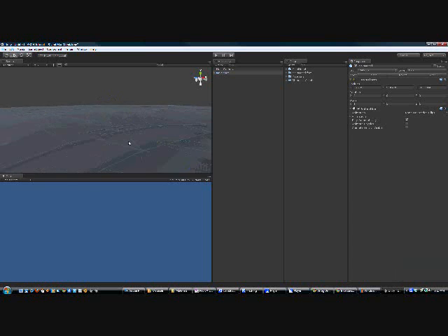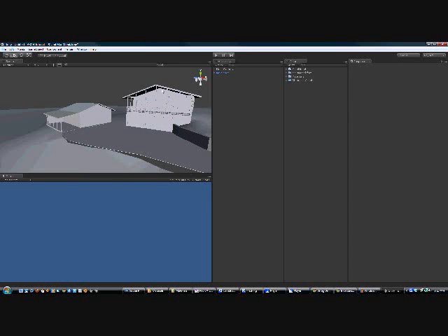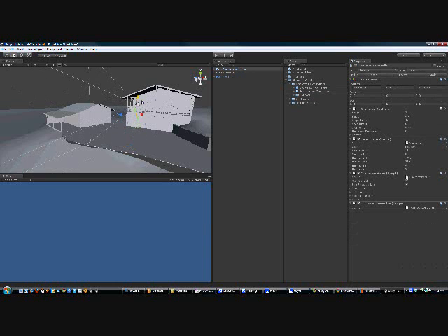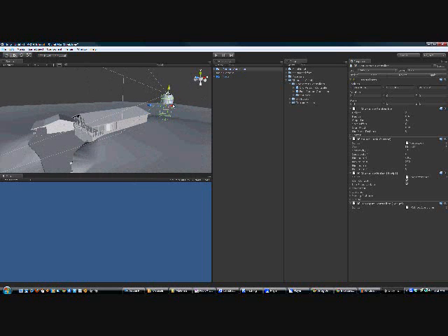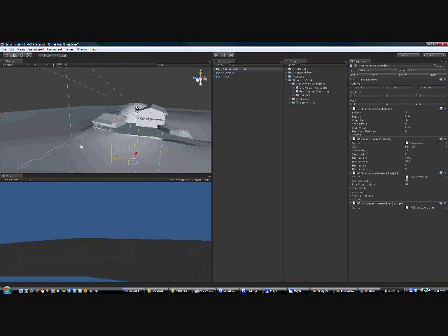And here's the model. Again, it's a very simple model, but it's here in Unity. And now what I would always usually do, and I don't know if this is proper protocol necessarily, but I find it to be useful, is to go into your standard assets, character controllers, and take a first-person controller. You'll see that it's sort of this medicine capsule shape, but that represents basically a first-person controller. So this would be like a person within your visualization project, and so you can move it in.